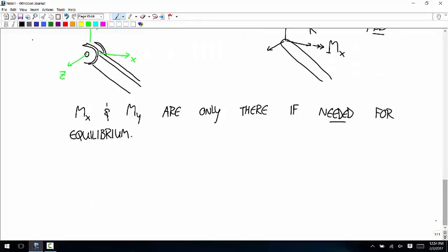And then the last category, joint category 6. I'll go into that a little more, but if you could do the statics problem without those moments there, and you could solve for the values without those couples included, then leave them out. That's what I mean. If those couples bring too many variables into the equation to solve it, then leave them out. I'll do some examples though.